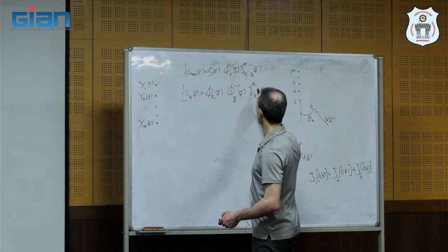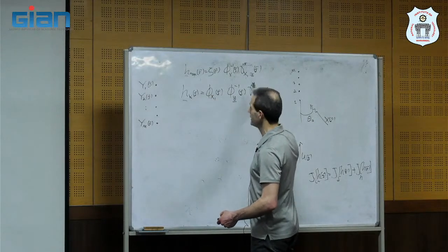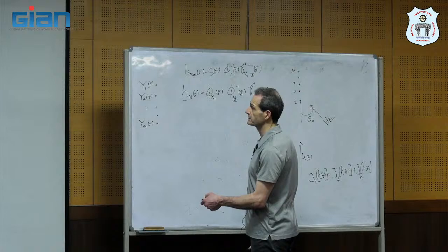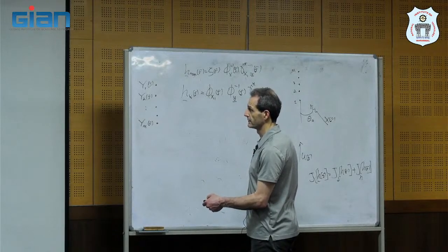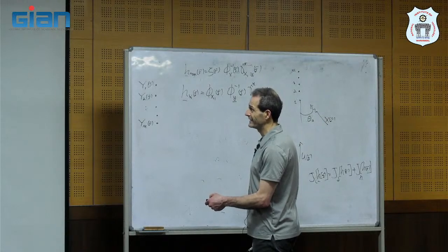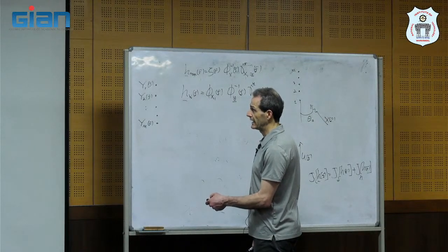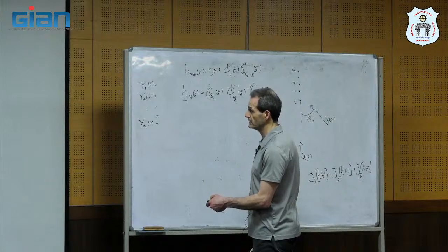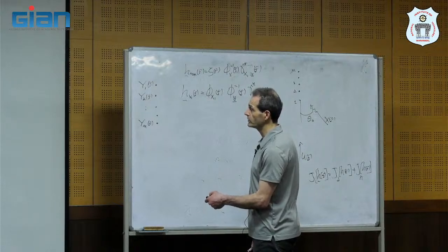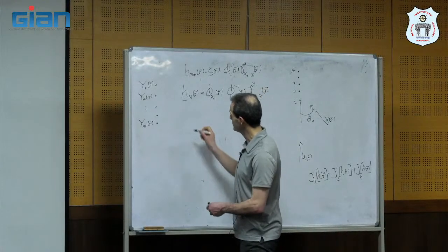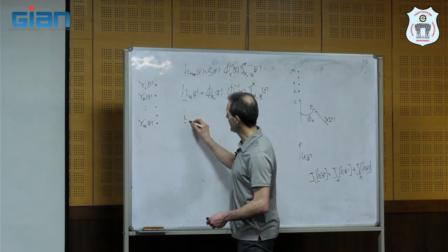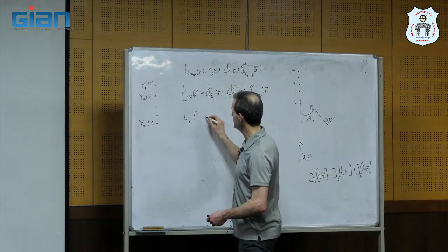I can write the Wiener filter by the coherence between x without the normalization, because phi x1 multiplied with this partially normalized is simply the coherence between the vector x and x1 complex conjugate. So I can write this vector as the coherence function or correlation function or matrix and multiply it with a vector of 1 and all zeros.